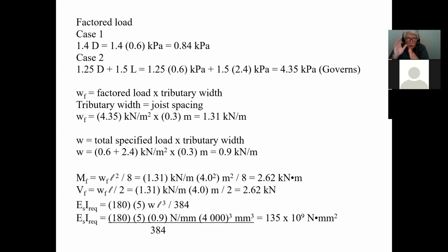Thank you. Okay, so that's how it works. Like I said, Adam, you have to keep in mind that L over 360 is something the standard doesn't require, but the National Building Code requires it. And if you want to always be safe, you should check both. In most cases, unless your dead load exceeds your live load, I can tell you right now, L over 360 will always govern over L over 180. So if it's susceptible to cracking or any materials we use.